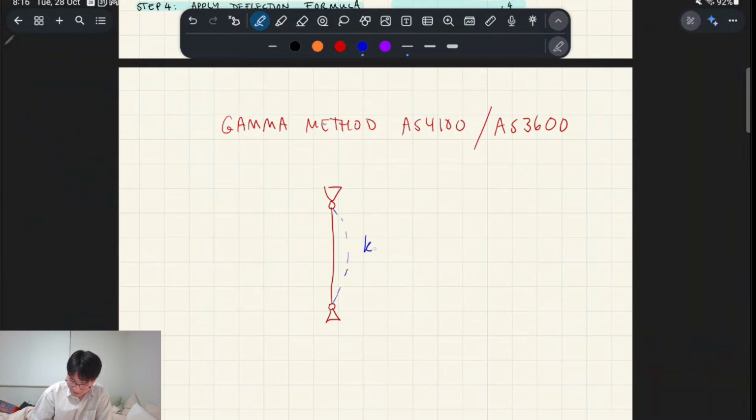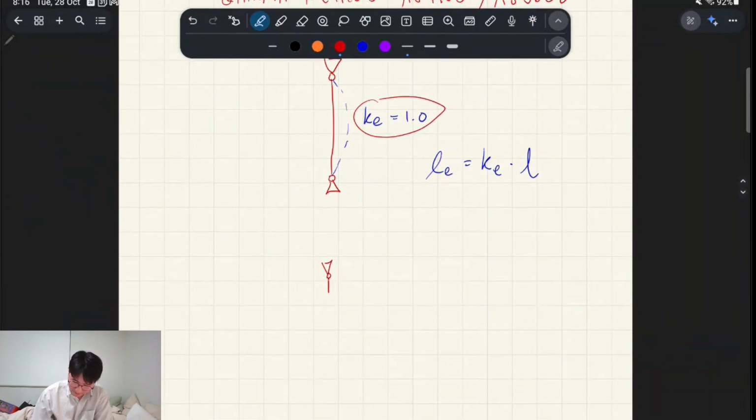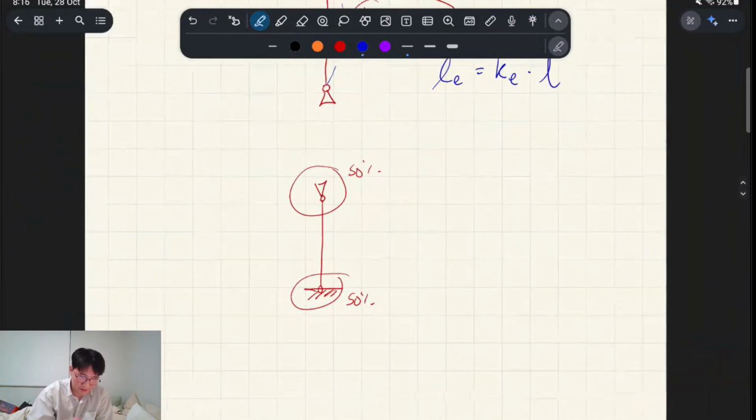You have an effective length factor, right? So your effective length is equal to your effective length factor times the length of your column or whatever. But basically, if you want to do a more thorough analysis of what KE is, your effective length factor, in reality, you might not have something that's fully rigid or fully pinned. It might be somewhere in between, like 50% in between or something, just ballpark. And it really depends on the stiffness of that connection / shape, and the columns and beams, everything attached to